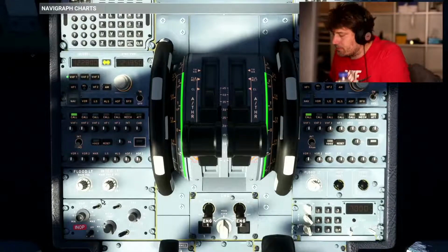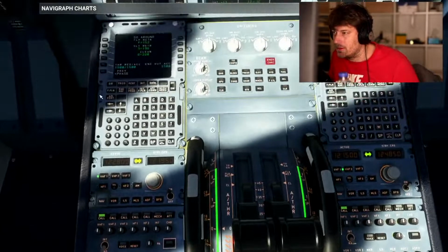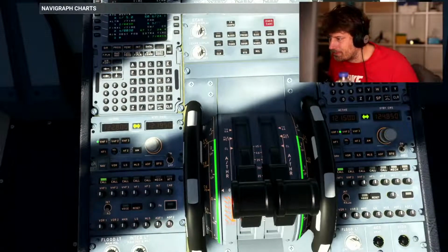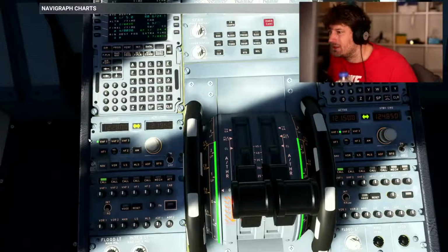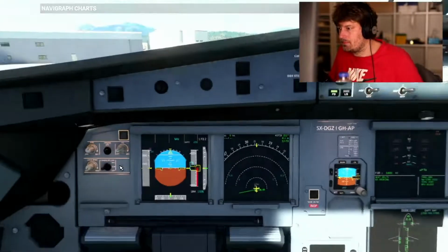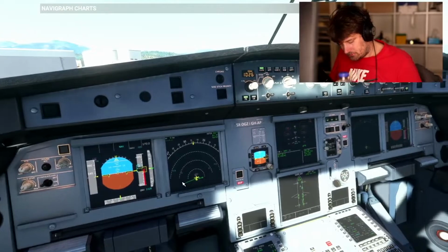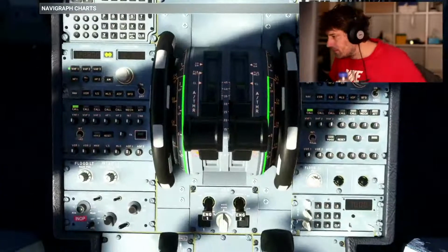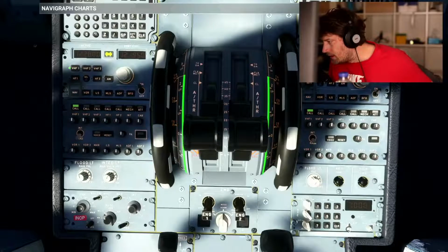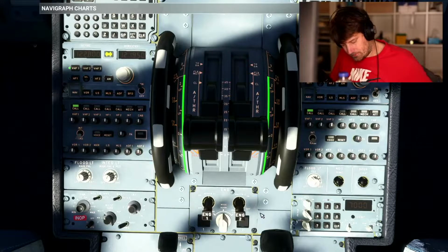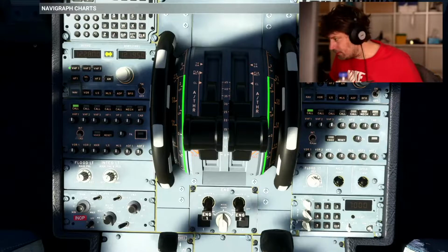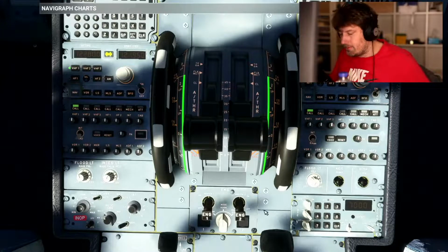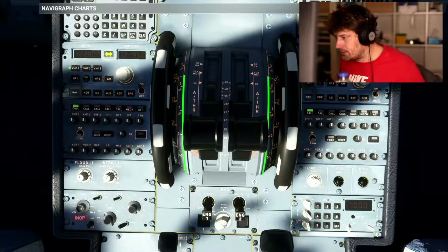And we'll also set the CG correctly. 24.4, 25, 24.4. TCAS to TARA above. Actually now it should still be on standby. While we taxi we have it on TARA. And then we can put the engine mode selector to ignition start and start engine number 2.